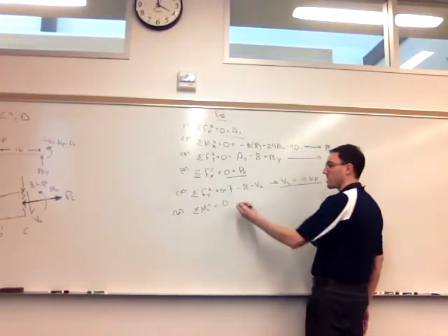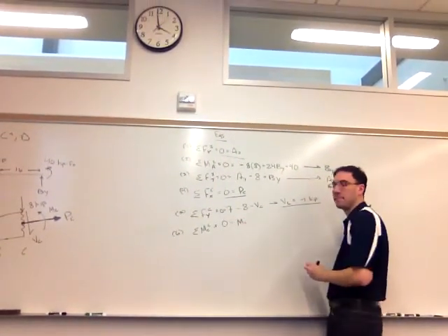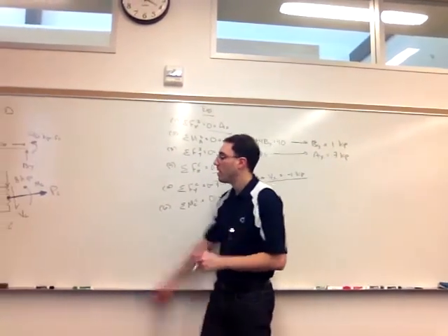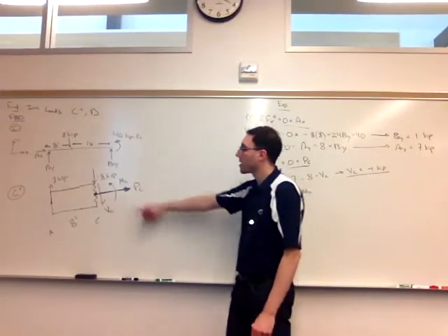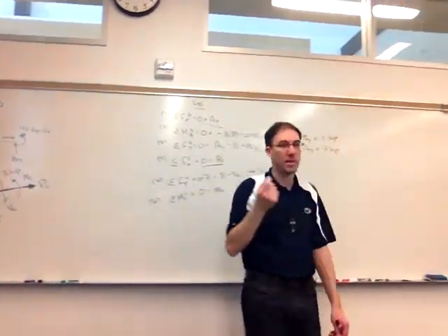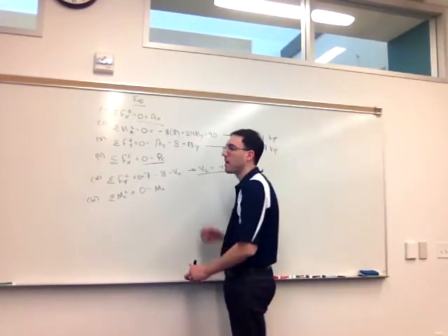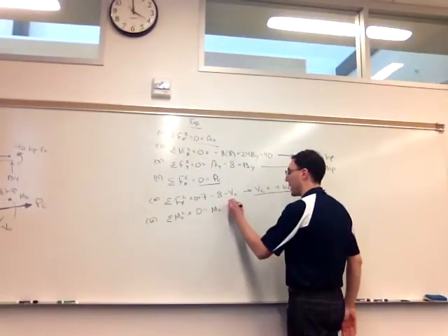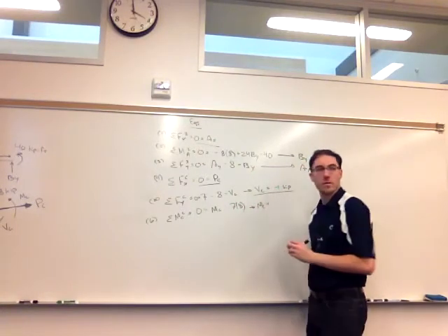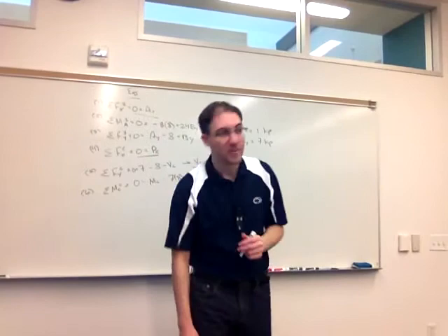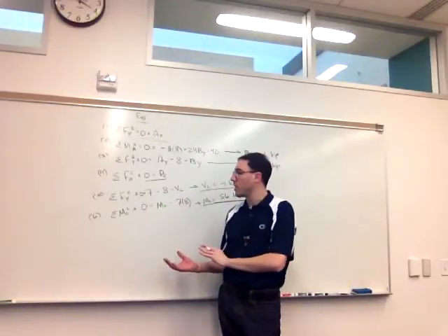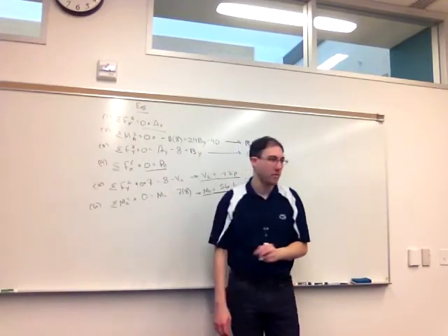So if I take the moments around C, I'll have that internal bending moment, M_C, I assumed was positive, or I assumed counterclockwise. P_C acts through C. The 8 kip force acts at least infinitesimally close to C plus, so I'm going to ignore its effect. Minus 7 times 8. So the internal bending moment is 56 kip-feet. Those are the 3 internal loads at point C when I take that vertical cut.